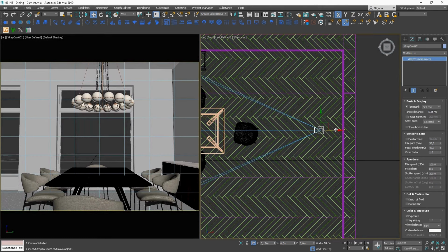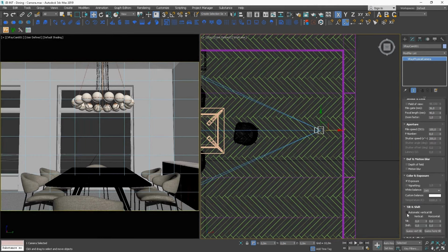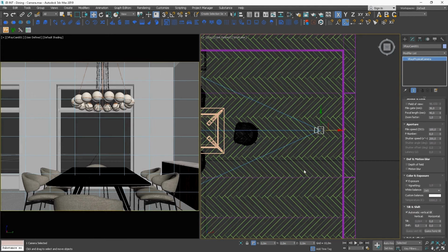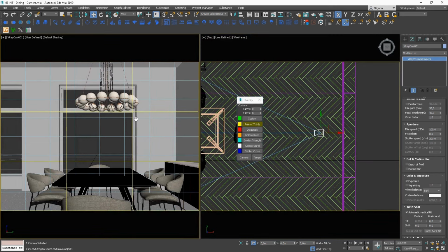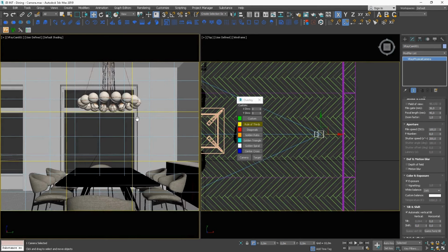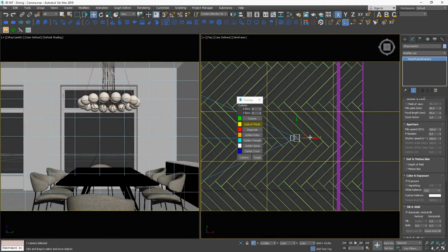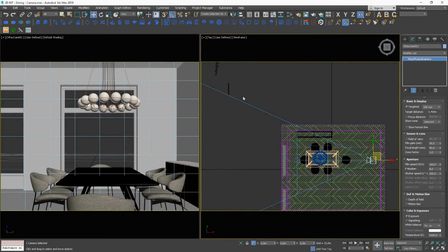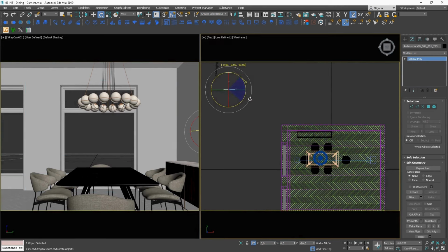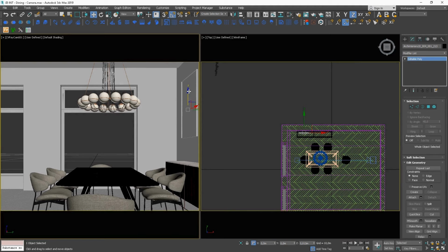By doing this, the vertical lines are not straight. To fix this, check Automatic Vertical Tilt. By using a composition script, make further adjustments to the camera and assets. I want to place the painting so it appears in line with the top of the window even if it is actually lower.